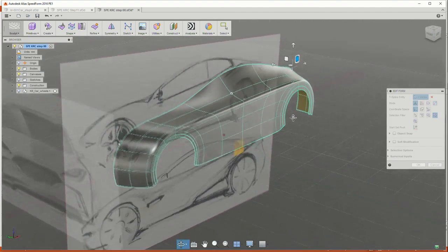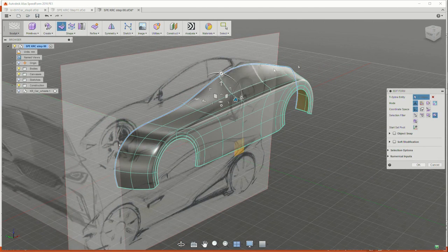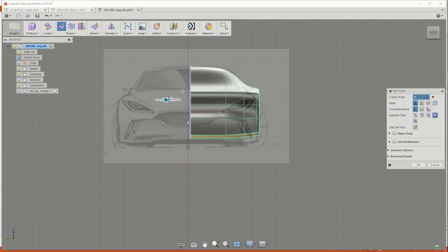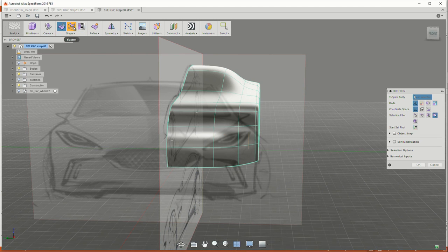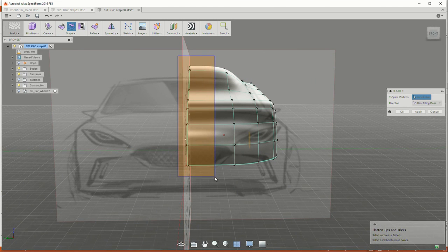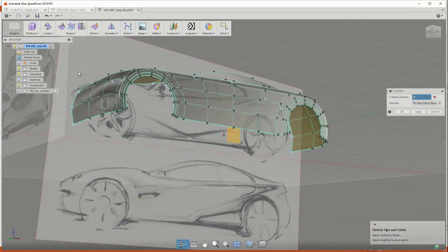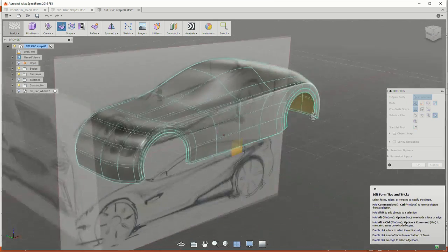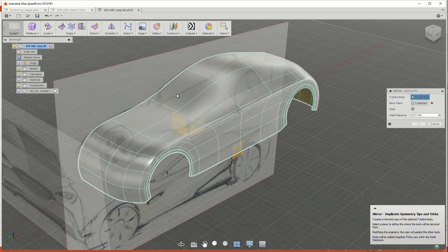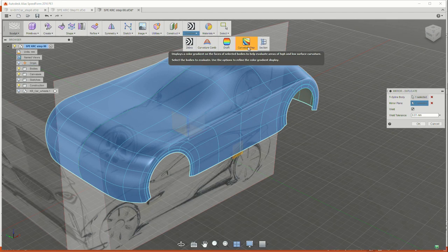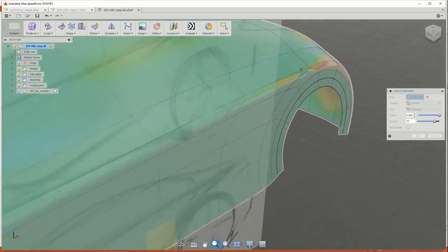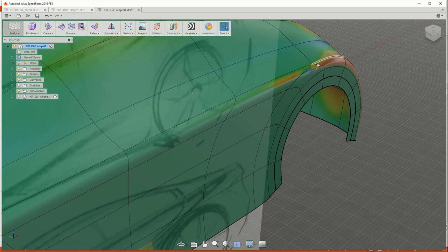So, all right, I got a general idea of what my shape is looking like. So guess what? I'm going to extrude one more time. Oh, I have to extrude one more time. Hold the Alt key down. Thank you, Rex. And then I've got the shapes close to the center, but I'm just going to go ahead and flatten this to the center line. So the symmetry will work properly. Put symmetry on it, maybe put some analysis on it. And we've got the start of a model. And then I can just start to define this a little bit more.